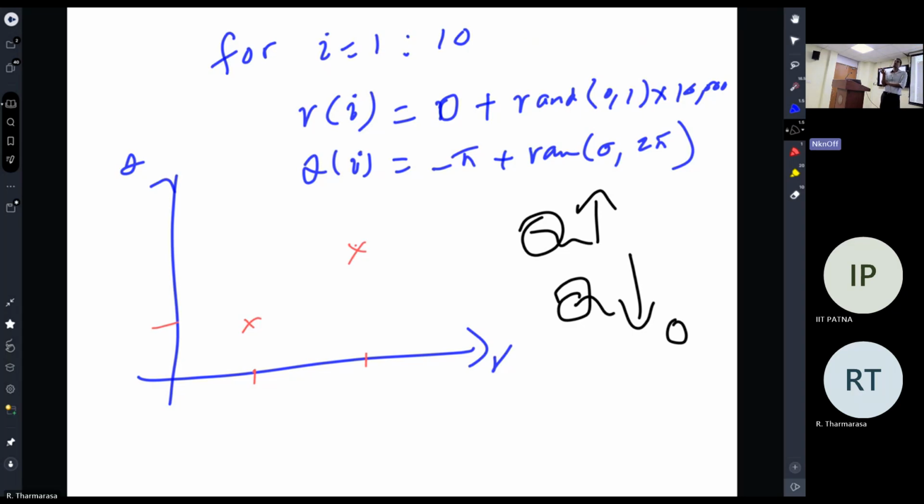And the other problem is that Q is not constant, right? In all our papers and algorithms for the Kalman filter, we say Q is constant. Q is not actually constant, it can also be time varying. In the Kalman filter we have a Q_k, but we drop the k after some point. But the Q fluctuates.